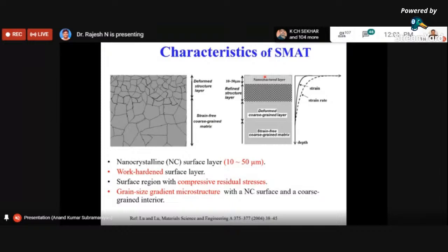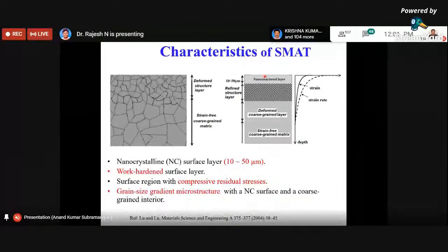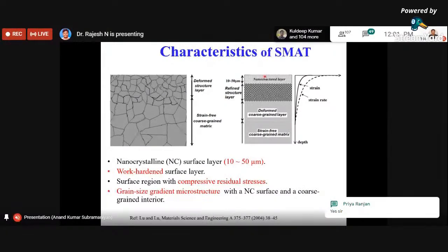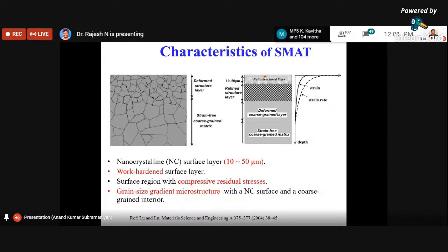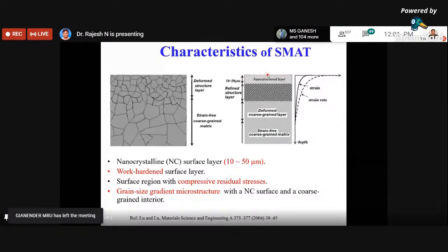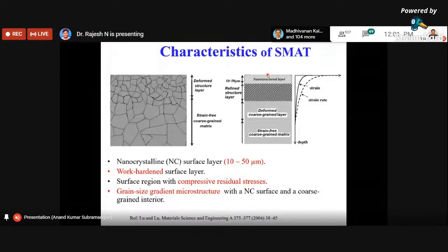For example, one could be electro polishing, right? People are using pulsed electro polishing as one of the techniques, which is a non-conventional post finishing technique, where you try to remove in a controlled way maybe a 1 micron or 2 micron layer, which will mostly be the peaks and valleys present on your rough surface. So electro polishing could be one potential technique to be thought of.